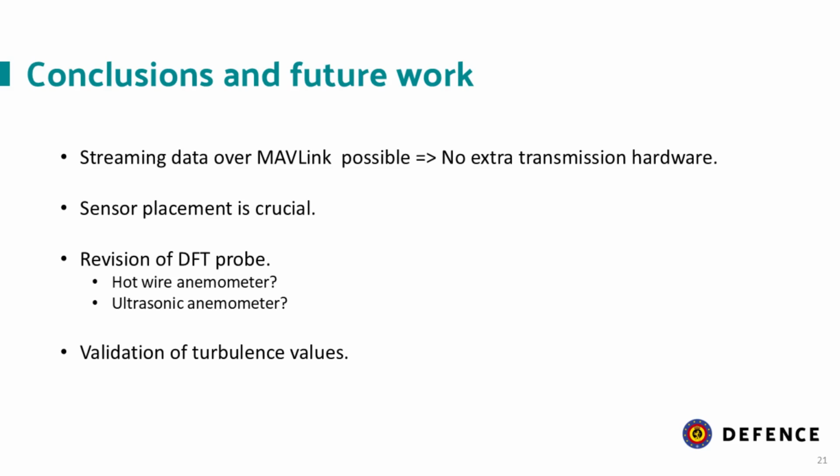We also learned that sensor placement is critical. Drones draw high electrical power, they have motors and batteries, and generate a lot of heat. Yet many of the parameters that we measured, like temperature, humidity, and pressure, are highly sensitive to this heat. Placing sensors on or near warm electronics led to skewed data, and this was a clear lesson in avoiding naive placement.